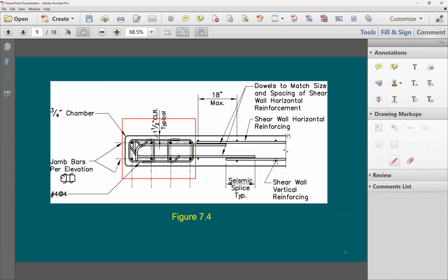Yeah, makes sense. How about number 5 at 14? So let me try. Number 5 at 14. The rebar I have is 2 rebars times 0.31, divided by the wall thickness, which is 16 inch, and the spacing is going to be 14 inch.